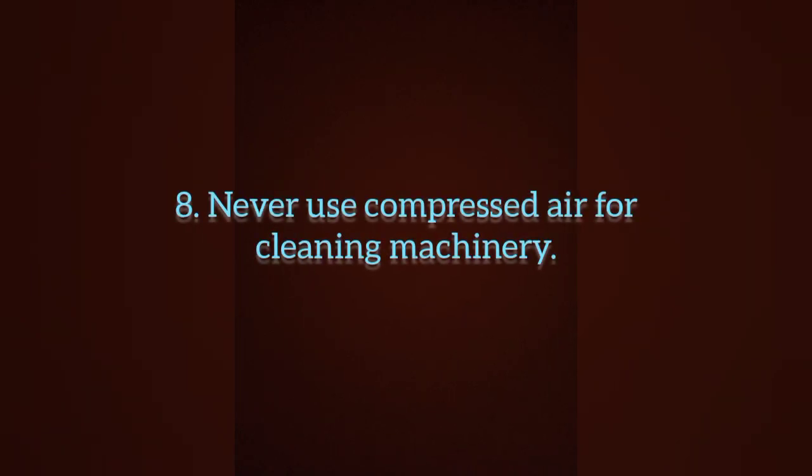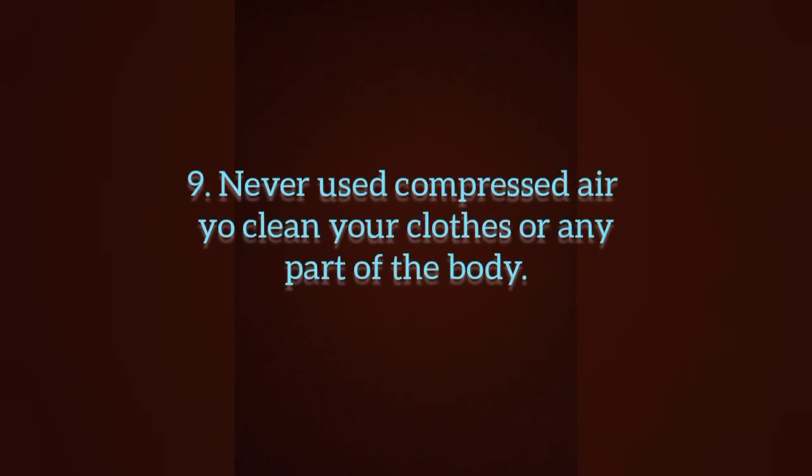Never use compressed air for cleaning machinery. And never use compressed air to clean your clothes or any part of your body, because it may become embedded in skin and eyes. In extreme cases, the air can be introduced into the bloodstream. So those are the general guidelines when we use machining or stationary machines.